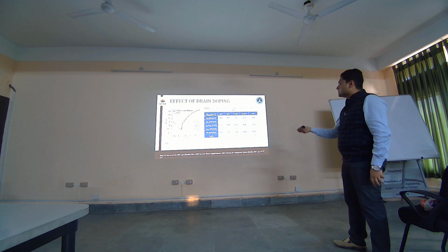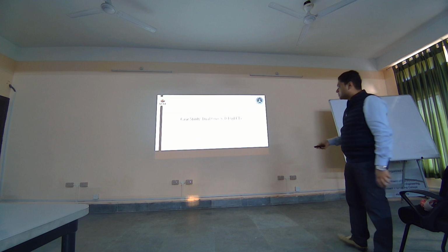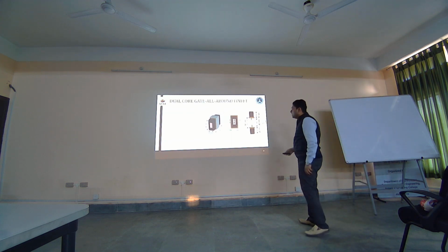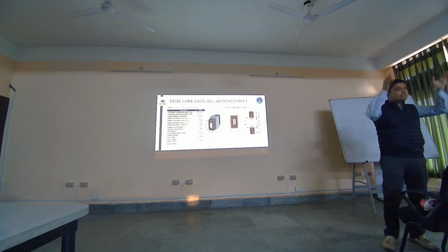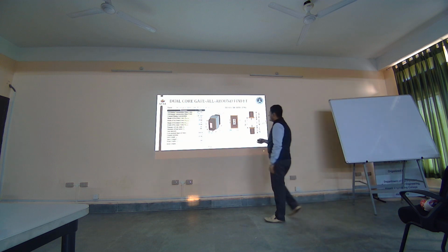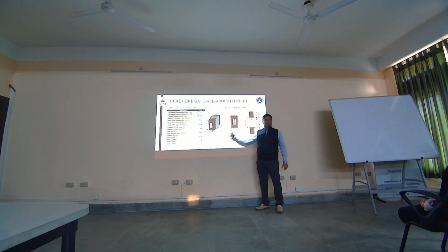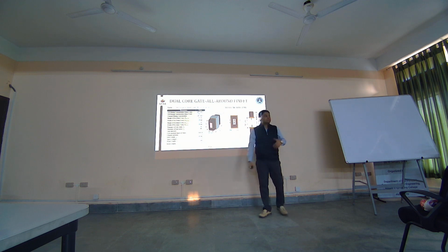We're not going to discuss these things in detail, and we're just going to go into the most important parts. So this is another one. FinFETs are 3D structures where you have the fin shape and then you have the gate wrapped around on all the sides. And we tried to get this once the ribbon FET was announced. We tried to take that device and simulate it, because that is how we understand the performance of new devices. You do not get all the results that Intel would have given us. So we wanted to check how this device performed.